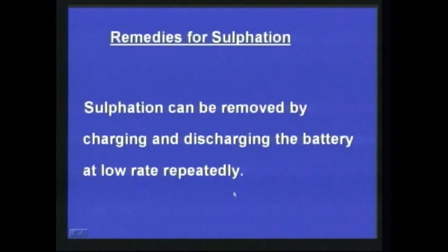Now we look into the remedies for sulphation. Sulphation can be removed by charging and discharging the battery at a low rate repeatedly.